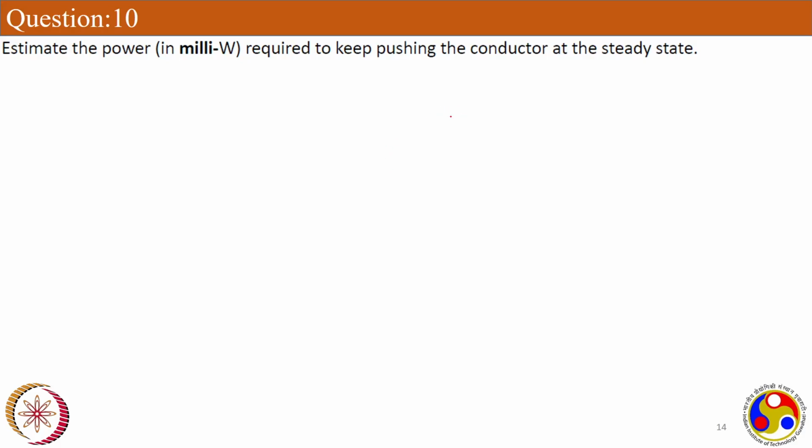Okay, power is equal to force into velocity. Now, what is the force? It was pushed at 100 millinewton, right? 100 into 10 power minus 3 newton multiplied by what is the velocity in meters per second? 0.9765. How much is this? Okay. Yeah, again it's 97.65 milliwatts. Yeah, that's right, Karan.